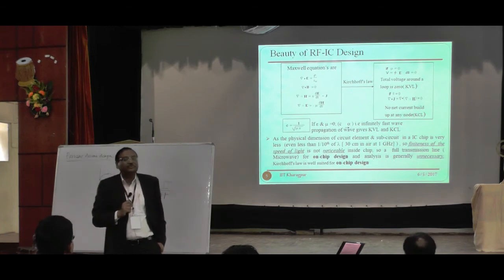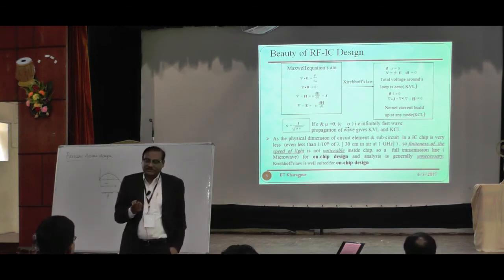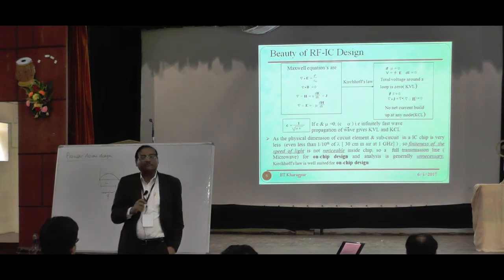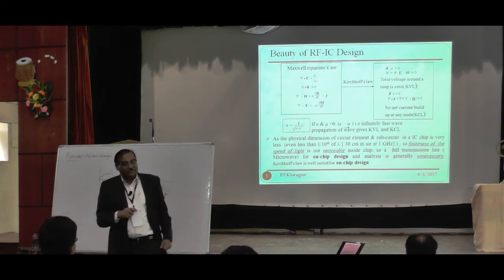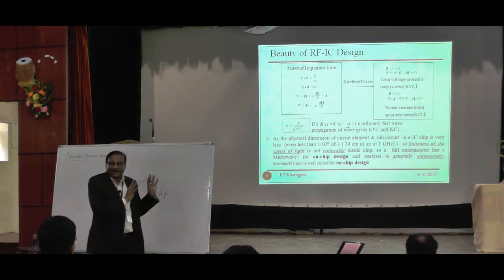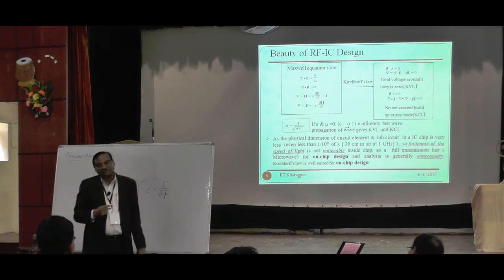In that case, you have to use Maxwell equation based solutions: HFSS, I3D, ADS, Microwave Studio, all those 3D or 2.5D softwares. So I say that from the antenna up to the device, it is all Maxwell, but from Maxwell to Kirchhoff's current law and voltage law, especially the small signal AC model, go to the device.